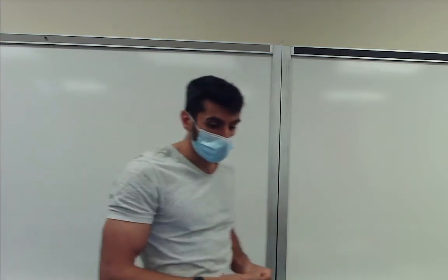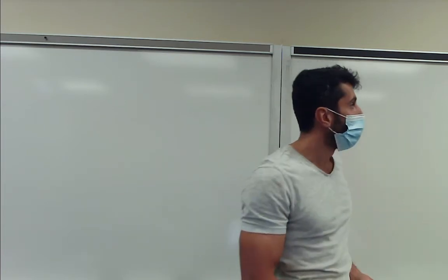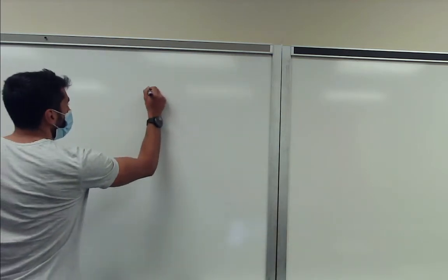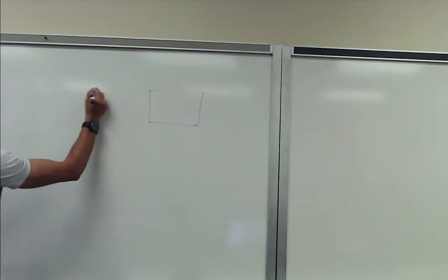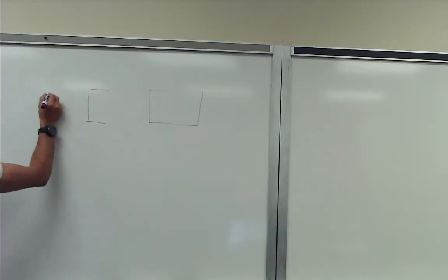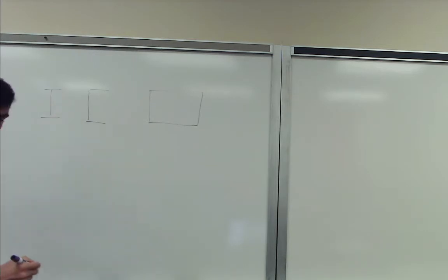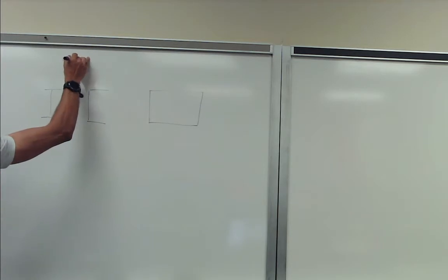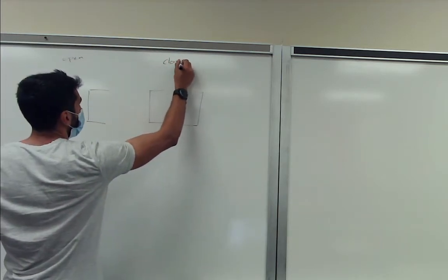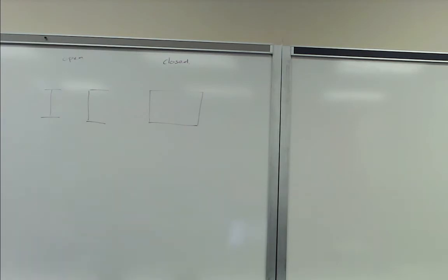Okay. So the next topic, we're basically going into closed sections. Again, say for example, we have the wing box we just showed. We compare it to our C section or our I section. So we said for an open section, these two are considered open, and this is considered closed, of course. For the open section on the left-hand side, we always said we're going to start at a location where we know that the shear flows start at 0.